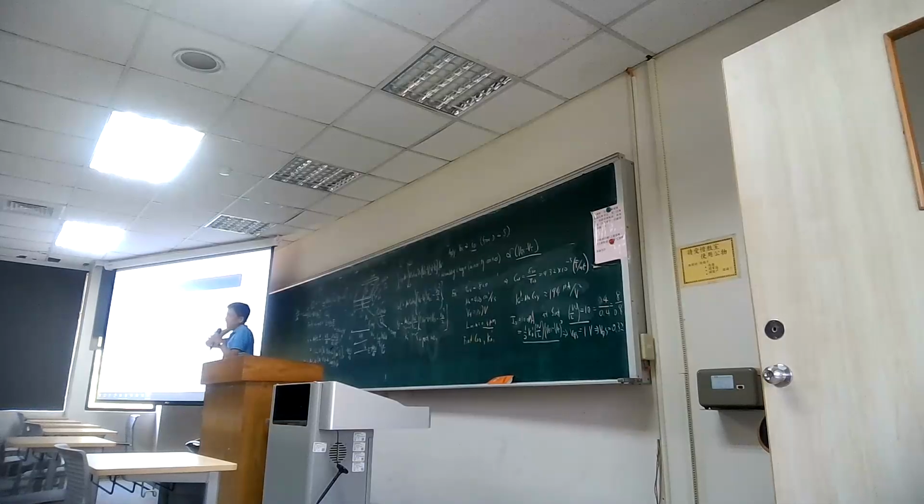What about mu? So how do we change mu? What is mu? Mobility of silicon. Can we change it? Maybe slightly. We can use strain or stress to slightly change the mobility. But maybe not by much, so it's typically not a good way.